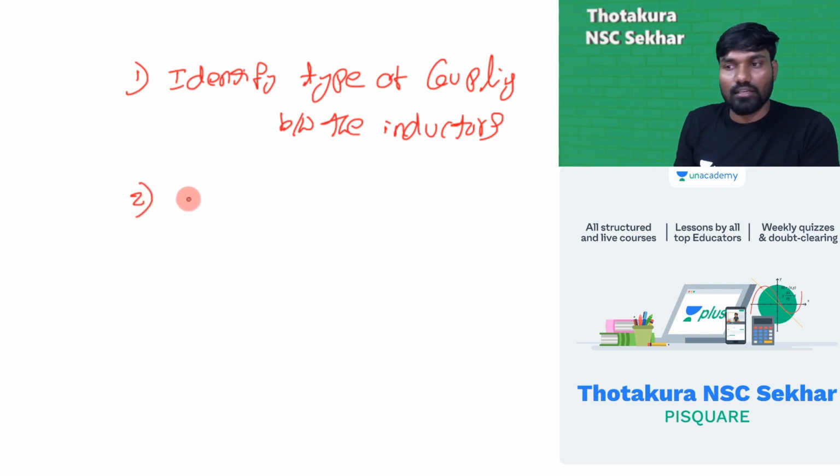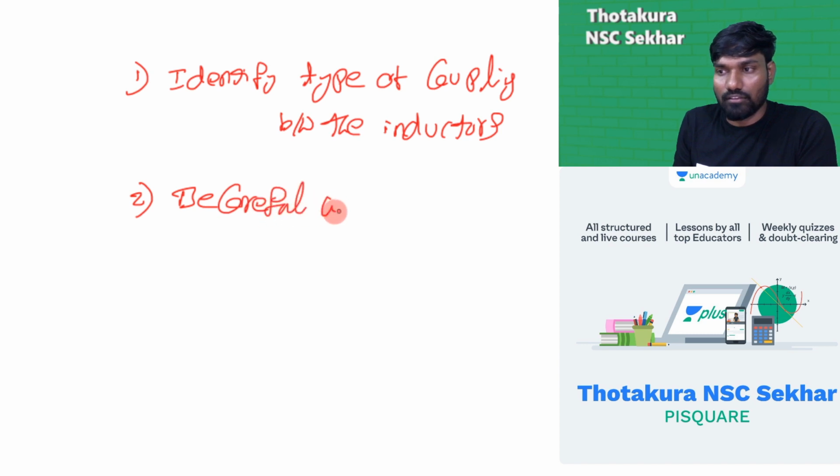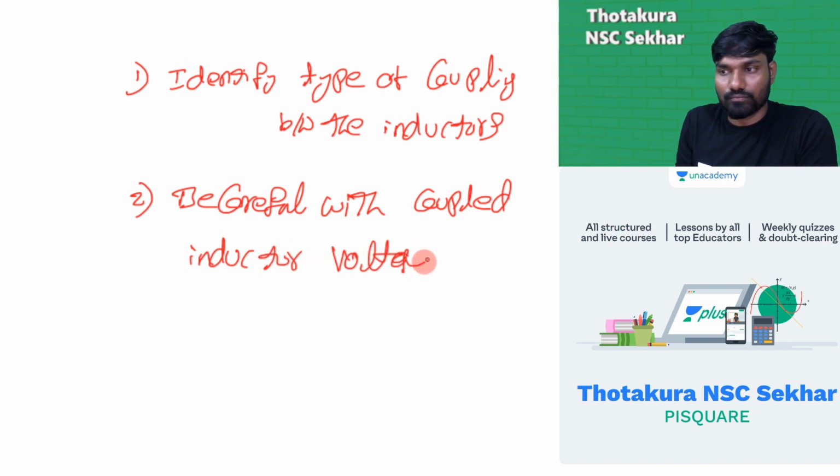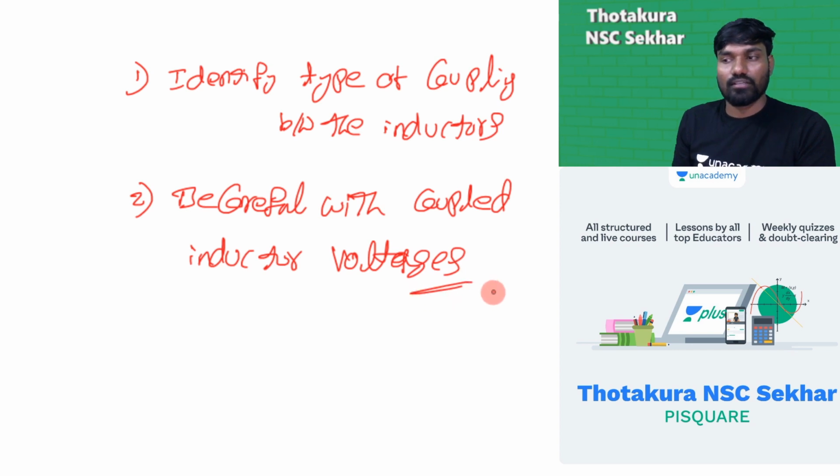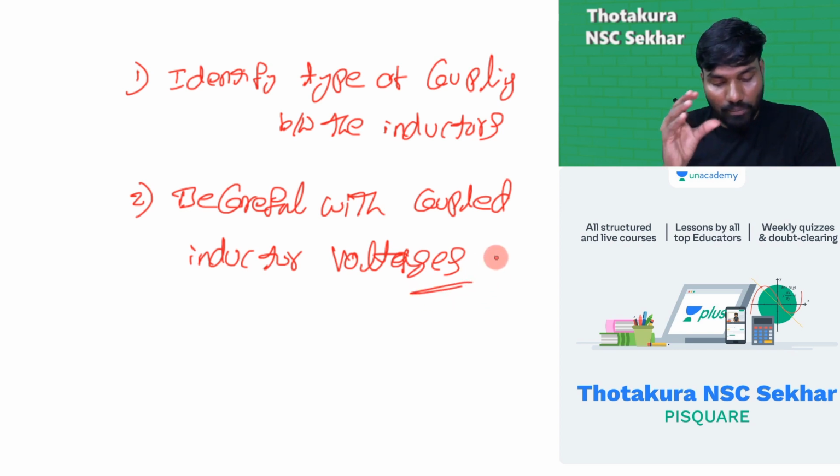The second one, be careful with coupled inductor voltages. When you want to find coupled inductor voltage, you should be very cautious, because it has 2 terms at least.